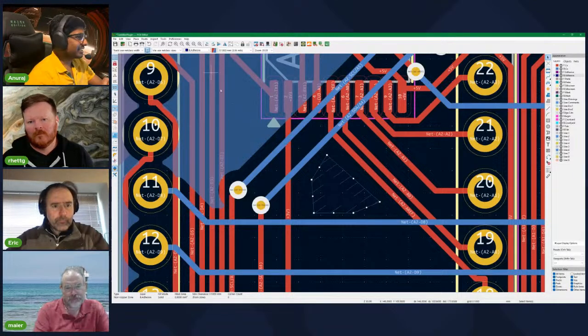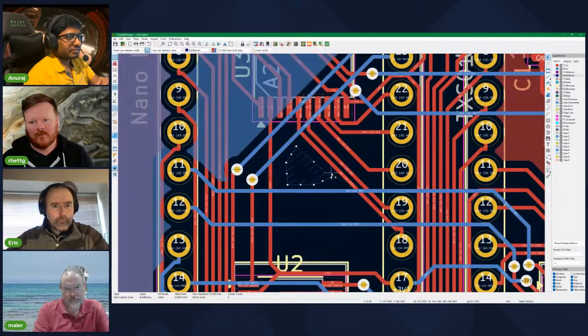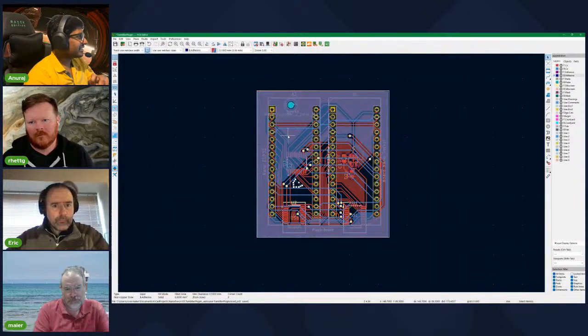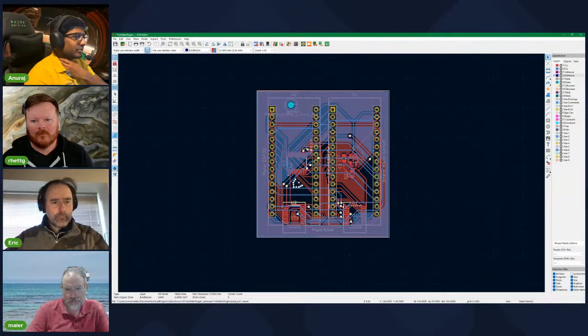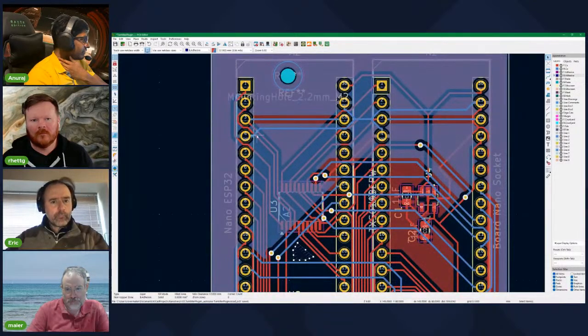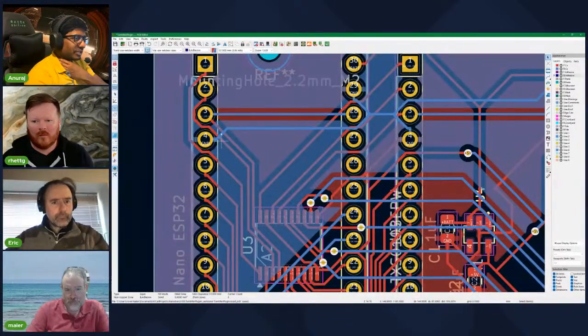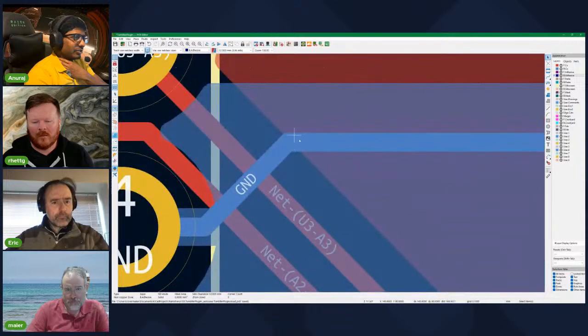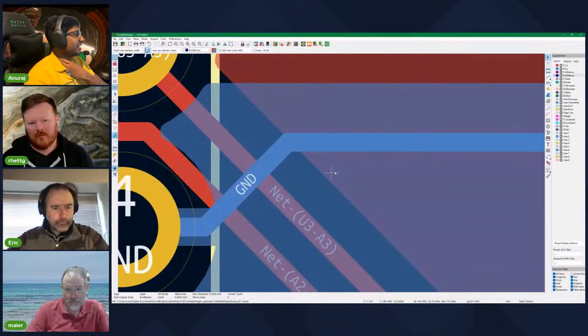There might be some electrical reasons for it, because in high speed circuits it matters. This is not a high speed circuit. I think it's because of EMC radiation. What the ground plane does is absorb many of the electrical signals. There are also tolerances about the angles between traces, because in high speed circuits sharp angles will cause some problems. But that becomes really specialized knowledge, and I don't have that much knowledge.